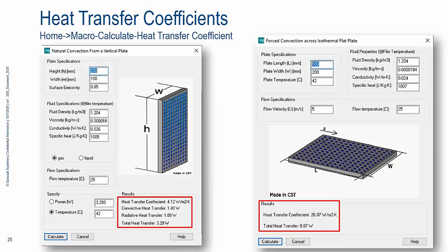If you're modeling a forced convection situation, like if you have a cooling fan or liquid cooling devices, you don't have to worry about radiation that much. You can still turn it on, but many people turn it off, not modeling that, because that could be your buffer or your design margin. So much for the fundamentals, and hopefully that gives you a good feeling of how heat transfer works in general.